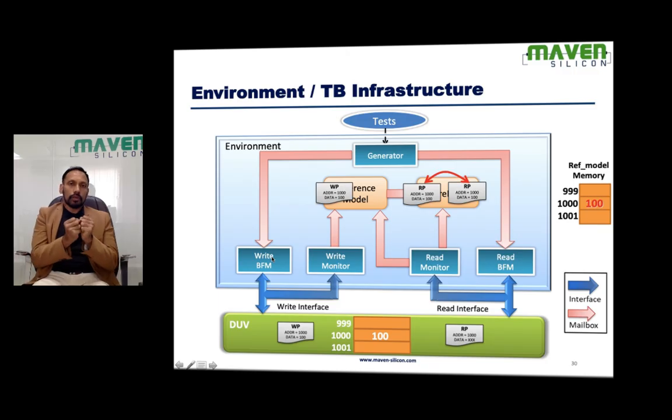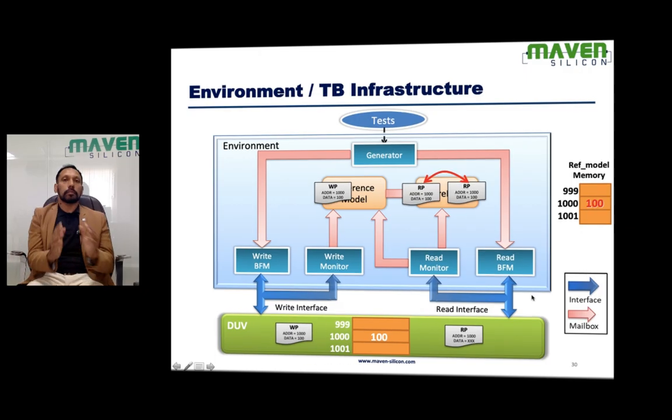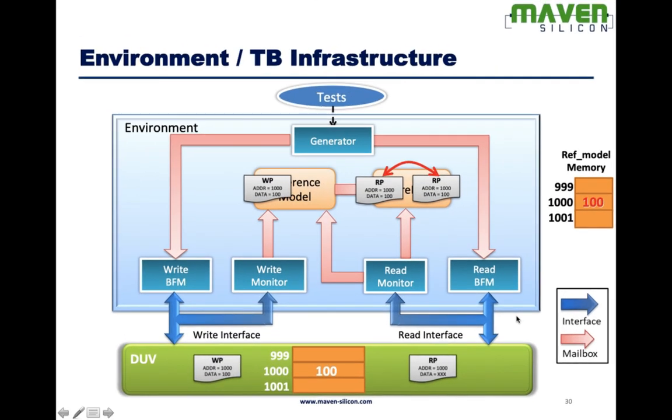When it comes to collecting any reference data, when it comes to collecting the output values, we always need to sample the DUV pins. So the methodology says whenever you come across any interface, you connect driver and monitor with the interface. So here, write interface, write driver and write monitor. Read interface, read driver and read monitor. That makes you safe. All right.